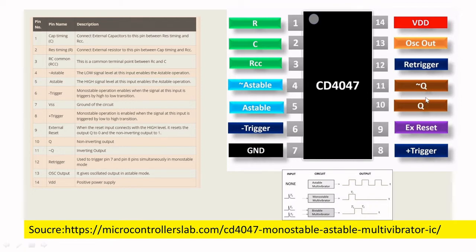The remaining things are already explained. On the 13th pin, we will take the full oscillation output, and from Q, one half of the duty cycle, and the other half of the duty cycle from the 11th pin.